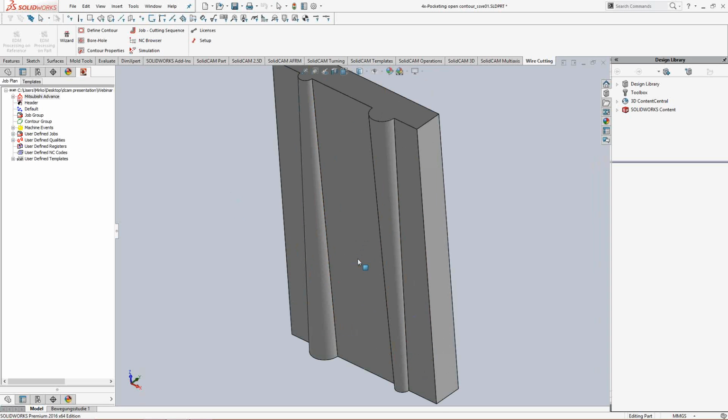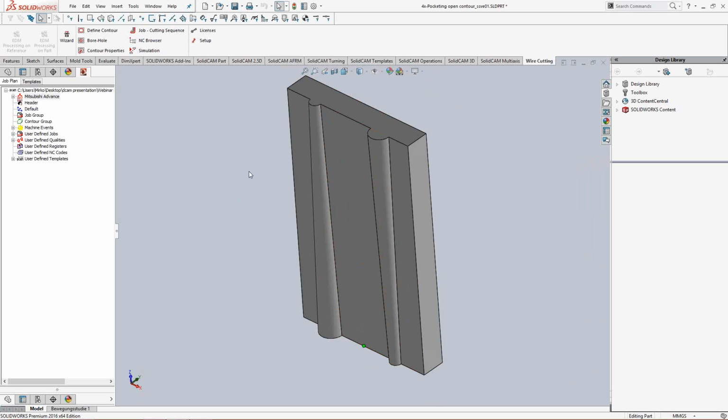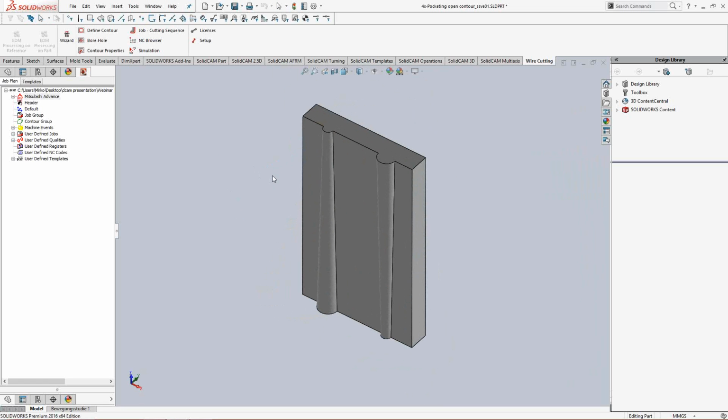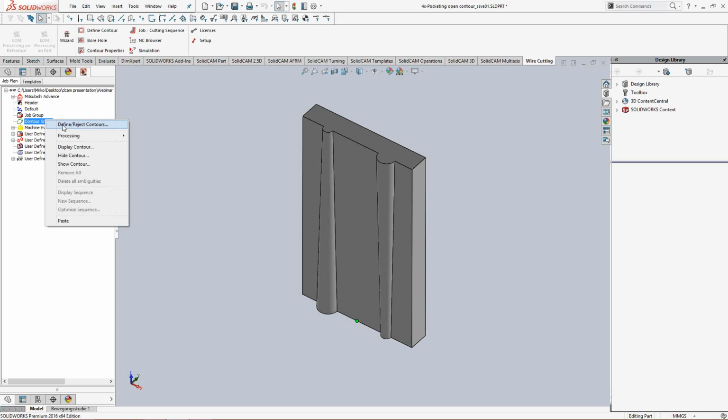As you can see here, we have this punch, and because we have two reversed lofts, we are not able to remove it with a single cut. Therefore, we need to release those lofts so we can extract this part without any problems. And now I will show you why we need to create our release and how to do it.